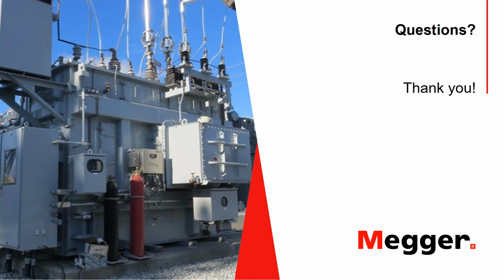Dinesh, what parameters are used to define a stable reading? Again, these are some very good questions being asked by the attendees. When it comes to the parameter that you use to define whether the readings are stable, typically, and when I say we, it's about any equipment manufacturer, we use that the reading needs to be 99% stable for a period of about a minute. In other words, the reading should not deviate by more than plus or minus 1% from its previous reading, and it should stay within the tolerance for a minute.